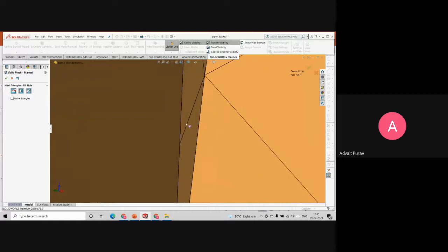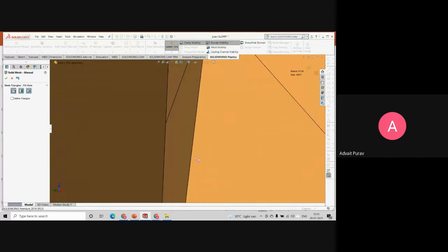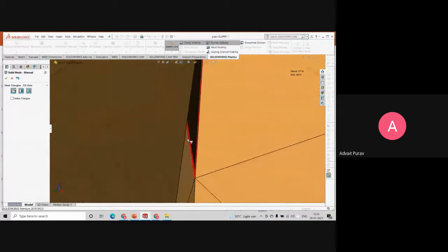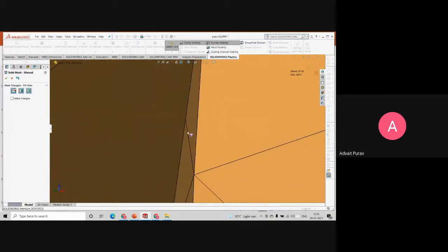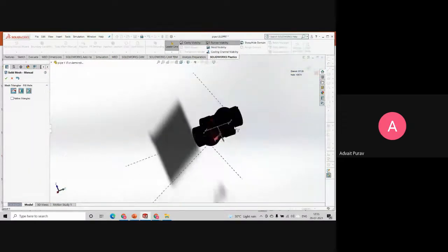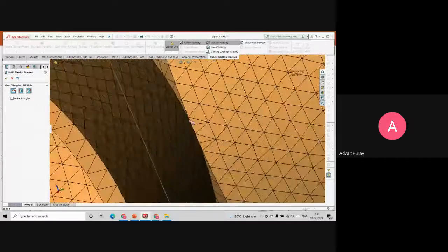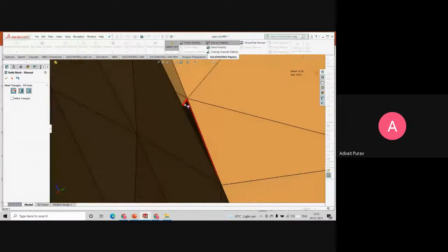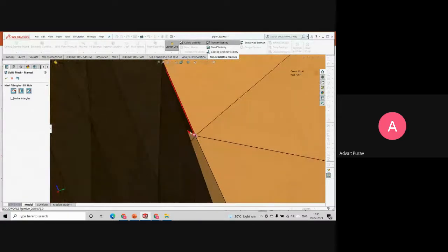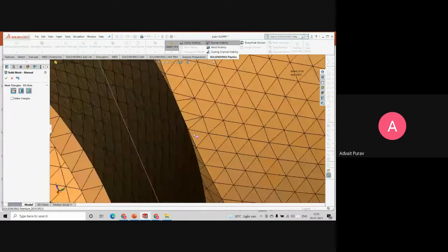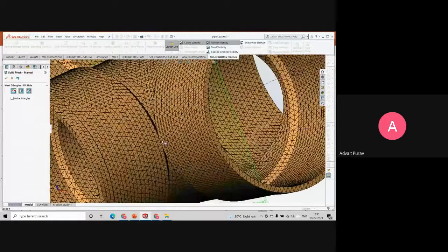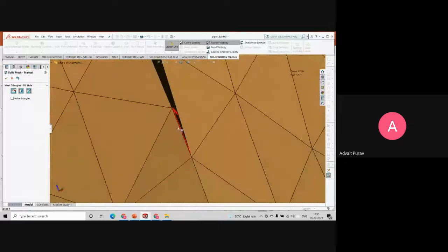If I just click on them, you see that the triangle gets completed, and the mesh in that particular part is uniform or correct. So I can just eliminate these parts like this, and I can do the same here as well. This is very important, and you should definitely refer to YouTube videos on how to do this, since everything is covered there. But you have to keep on refining your mesh until you get the least number of intersection and non-manifold elements.